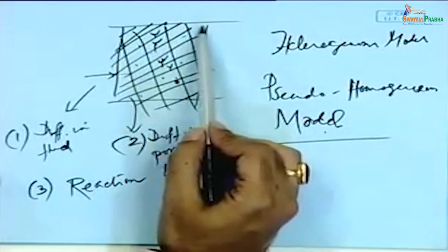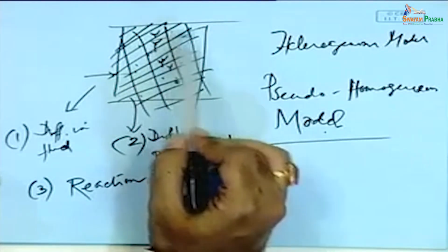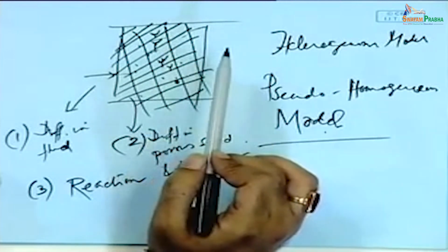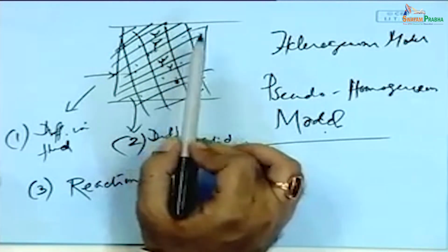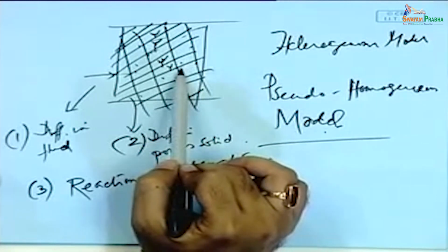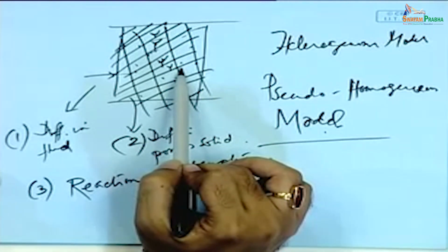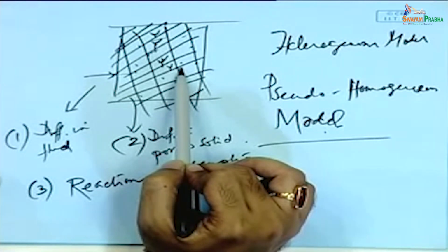The assumption is that you homogenize over the entire matrix. So you assume that these receptors are present uniformly in the entire matrix. So what you do is figure out the total number of receptors and the reaction rate for each, multiply that to get the total reaction rate for the receptors, and then divide it by volume to get a volume average reaction rate. Is that clear? Once that is there, it is assumed that though these reactions are in principle heterogeneous reactions occurring at certain points, the whole thing occurs uniformly over the entire matrix. So this is the concept of a pseudo homogeneous reaction.